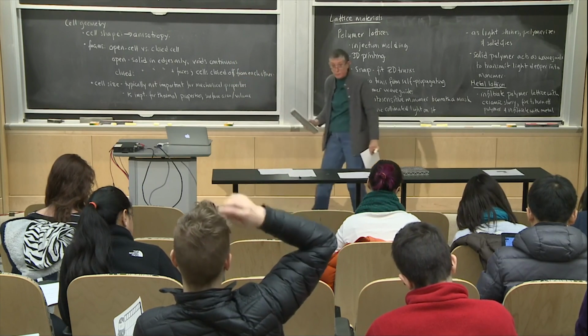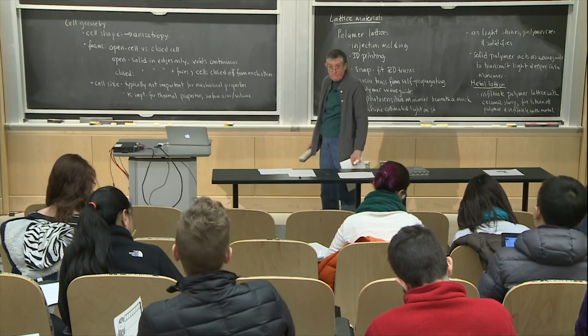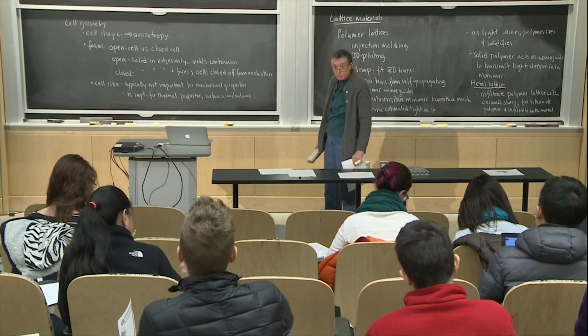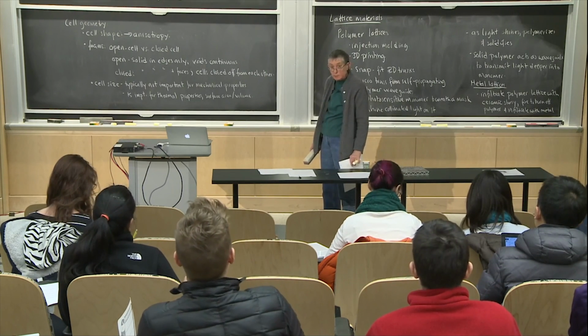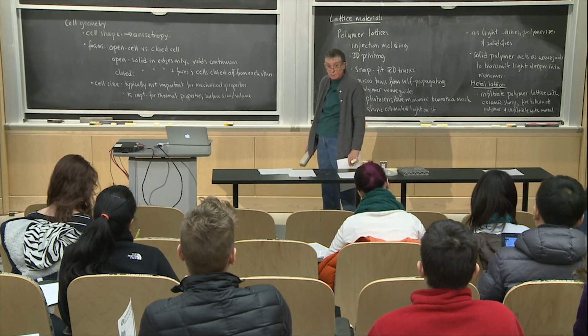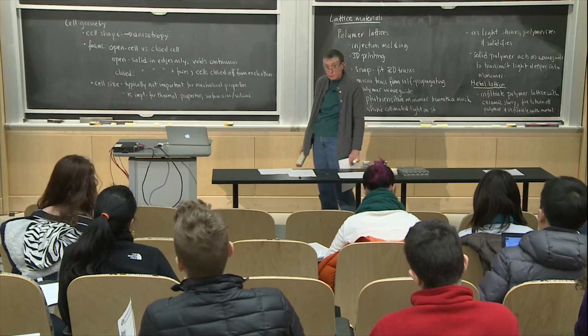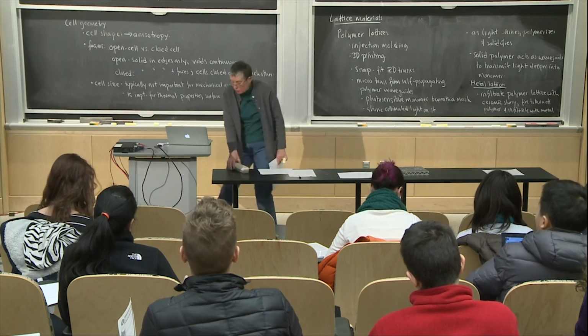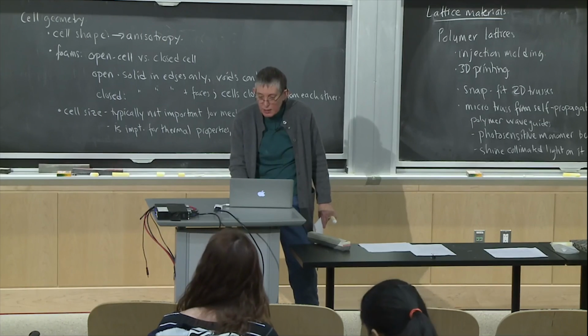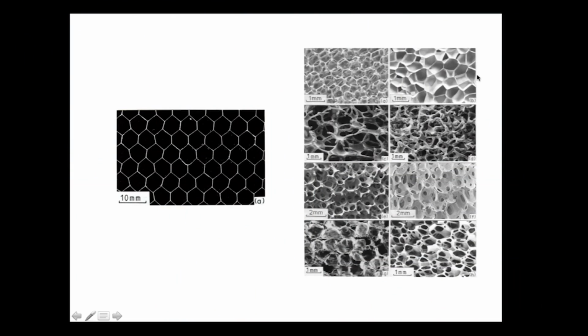Yes? So for the closed cell foams, because we can't really see it without cutting it, is it that all of the faces are closed, or is it some fraction of the faces that are closed? So if you look at this one on the top right here, they're pretty much all closed, right? But the reason we have this little picture down here is some of them are closed and some of them are open. So you can get ones that are in between, but typically, this is kind of unusual. Usually they're either all open or all closed.